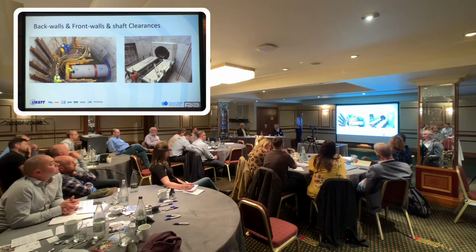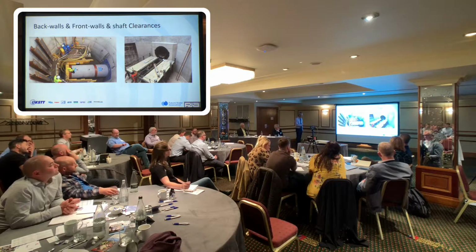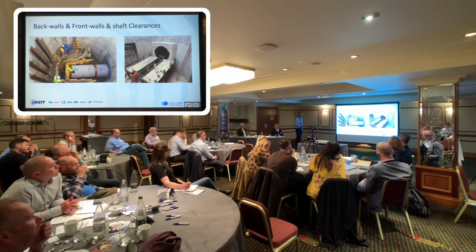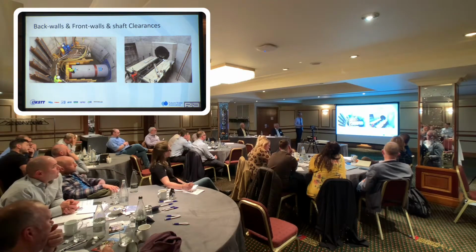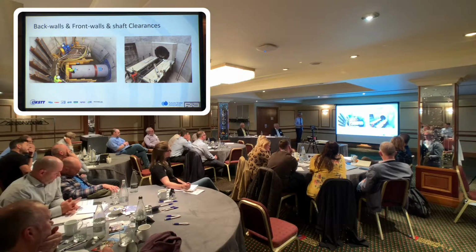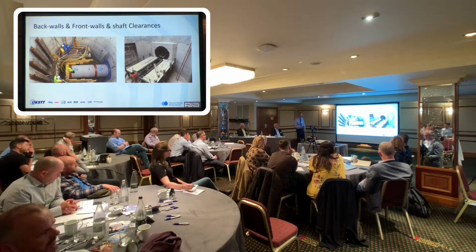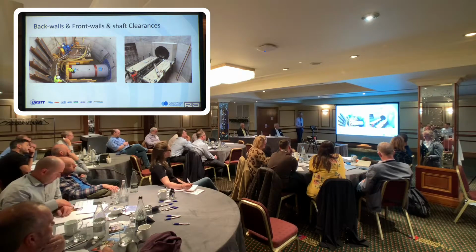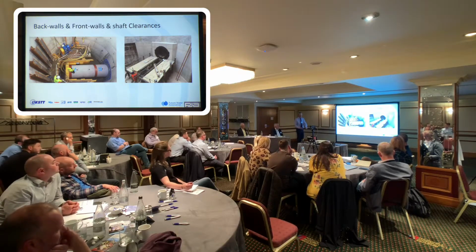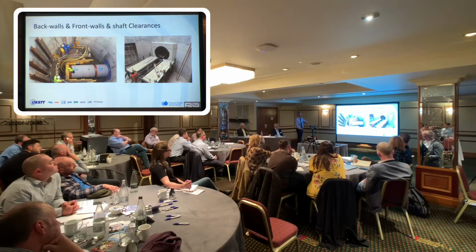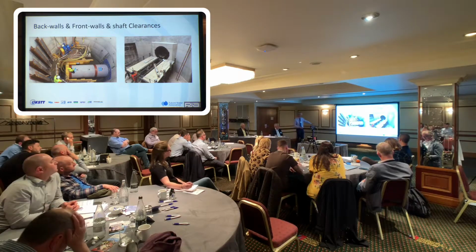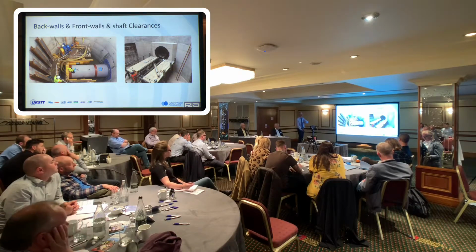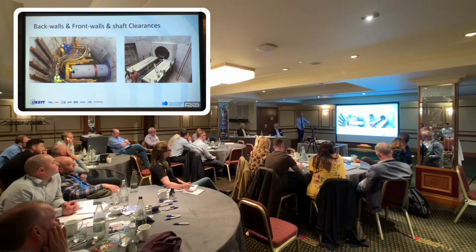So these, again, Jim's mentioned using beams to increase jacking load capacity at the rear of shafts. One of the things that needs to be considered when sinking shafts, and the depths of shafts and the top of base plugs, is that you need room beneath the pipe invert to take the seal and to allow the jacking rig to be placed below the pipe. So it's not a simple matter of a straight line out of the bottom of the pipe. You normally have maybe half a metre clearance between the invert of the pipe that you're jacking and the top of the base plug.